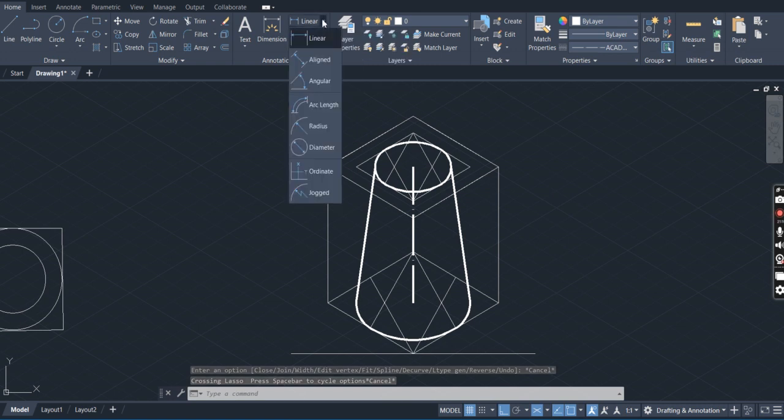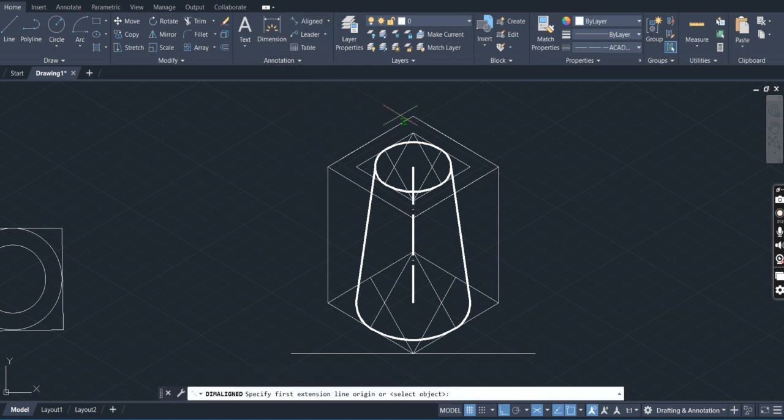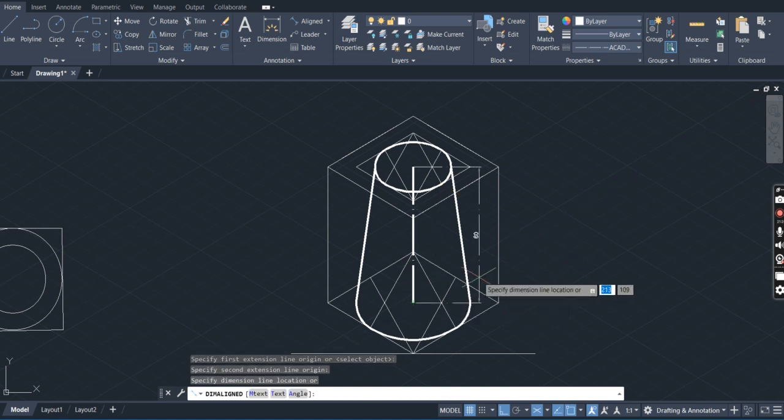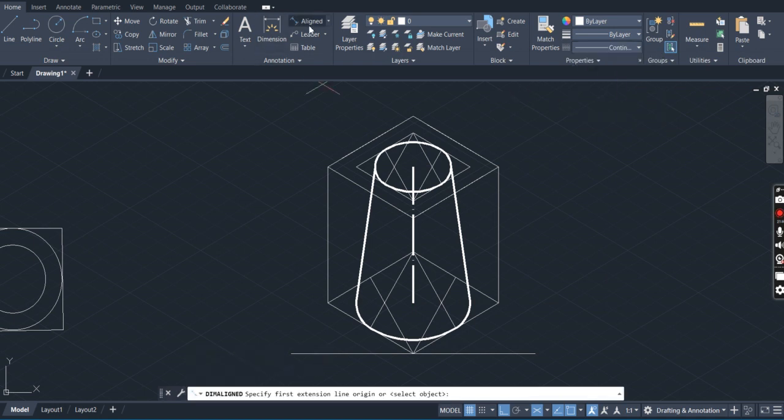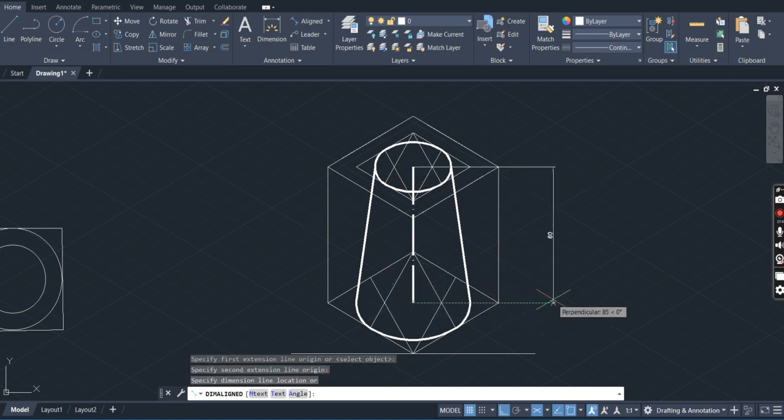In that we'll find linear or aligned. Because it is aligned, I'm going with the aligned system. So I'm selecting the axis height, the starting point of the axis height. I want to change this to continuous and go to align dimension, align, choose the first one and choose the second one and give the dimension.